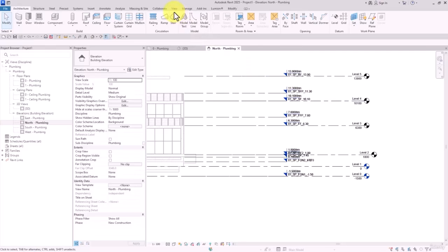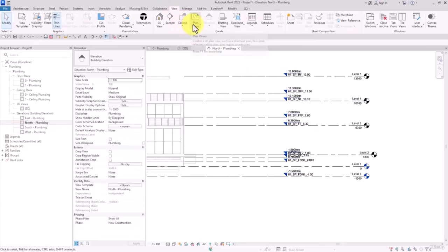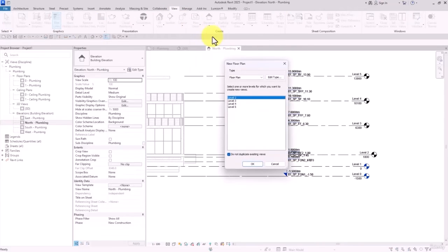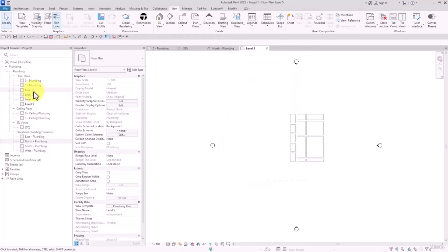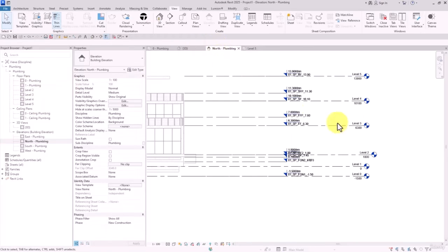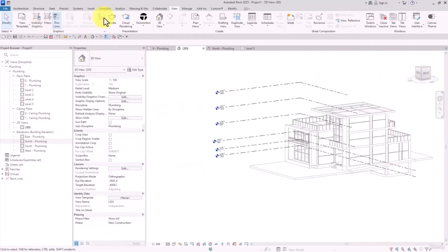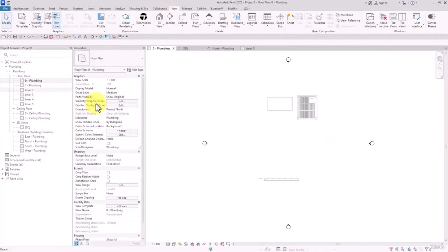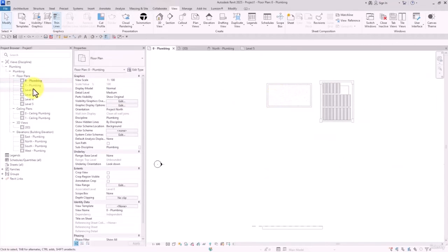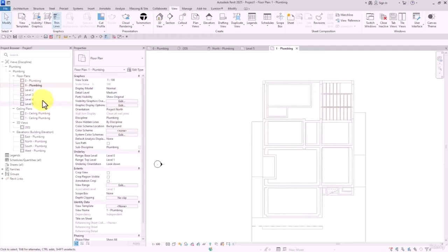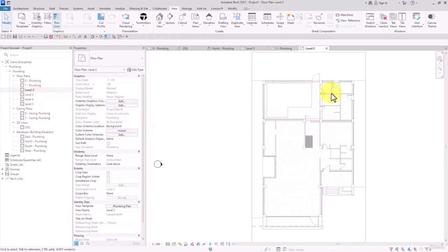And if you have created references by mistake, don't worry. You can go ahead and open up Plan View here, then select Floor Plan, and then we will see a list of the references that we have. We can select them all, for example, and then add them here in our list. And as always, you can go ahead and rename everything to whatever you want. So again, we can link files. We can link different files in our viewport. Check the architectural or structural file that we have as our base file. Find out what you need in your own project and start working on it.